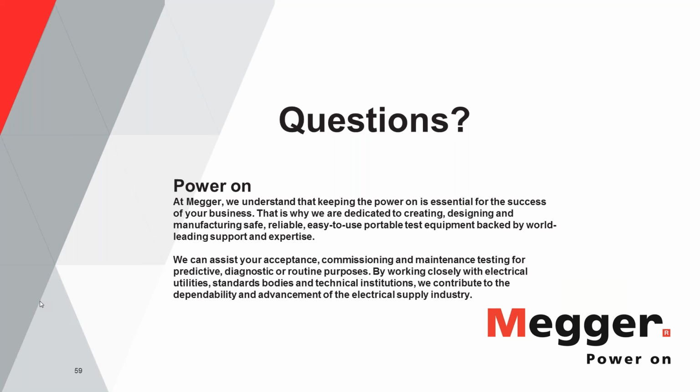Next question is, how often should your primary test set need to be calibrated? Industry standards about calibration for pretty much every test equipment is every year. But keep in mind that calibration might just be a verification, not an actual adjustment of the output parameters of the unit. You just need to verify that it is in compliance with the specs of the unit and what you need from the unit.